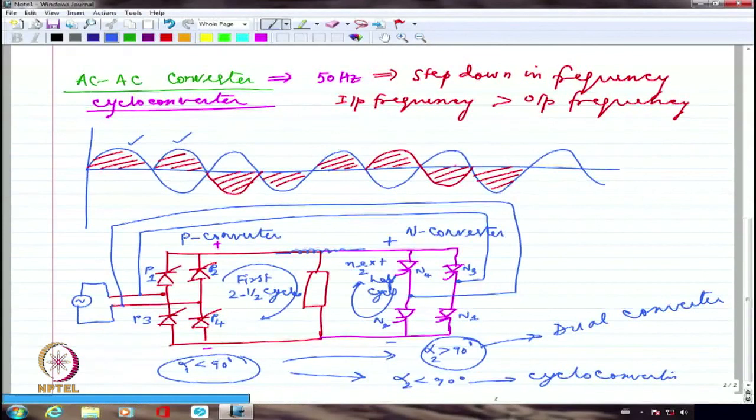So, this is single phase to single phase operation. I can have the same thing for single phase to three phase, three phase to single phase. So I can have multiple types of cycloconverter connections. So when I am talking about single phase to single phase, that is full wave, because I'm not leaving out the other half. I'm always using both the halves of the input wave, whether it is positive half or negative half. So it is a full wave controlled converter. What I have used is a full wave, fully controlled converter.